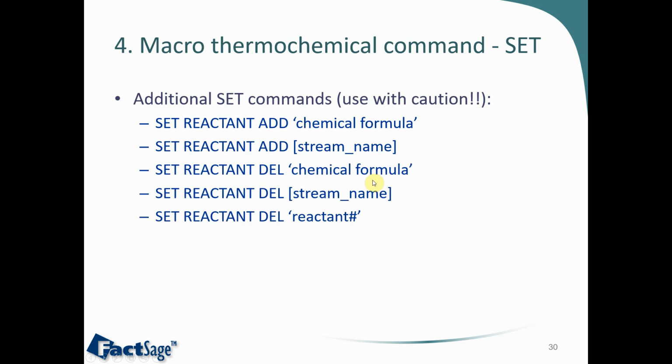You can also delete an existing reactant with the command set reactant del, then specifying either the chemical formula, or the stream name if it's a stream, or the reactant number, meaning the position in the reactant list.